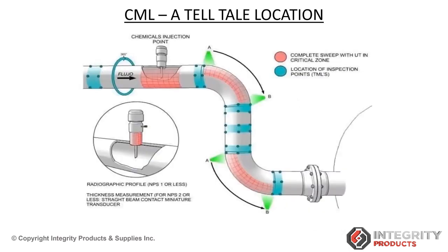As I mentioned previously, API 574 talks about the investigation of the damage mechanism, and 570 talks about the investigation of thickness loss. But there is another interesting thing about the inspection ports or CMLs: they are a telltale for process optimization as well.